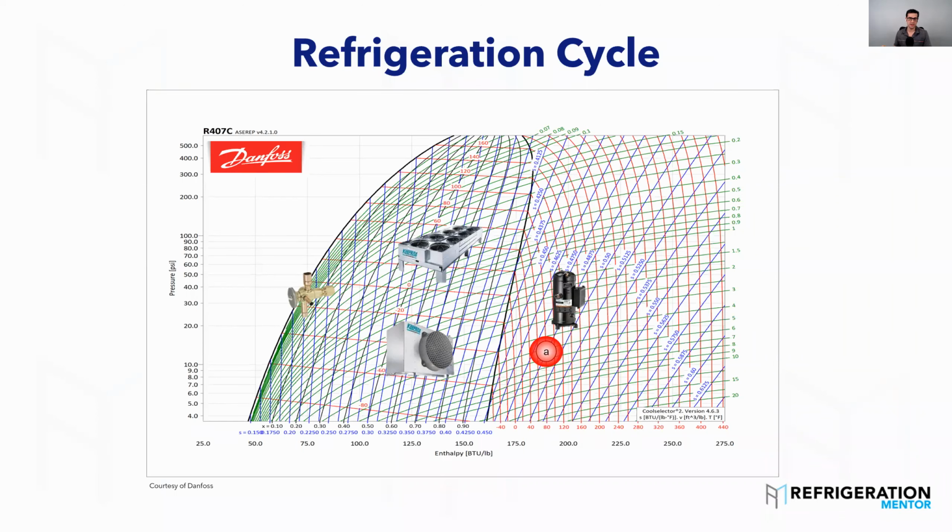That compressor turns on. You get power to it, and it starts up. And what happens is you get something called a heat of compression. That compressor takes that low pressure gas, starts to squish it, compresses it, this is a vapor, and discharges it out. What happens next?